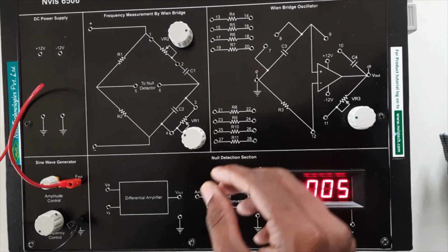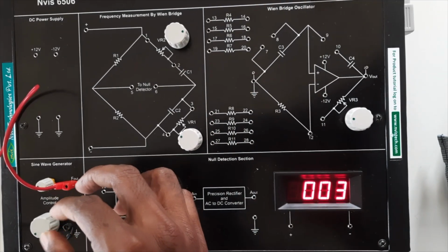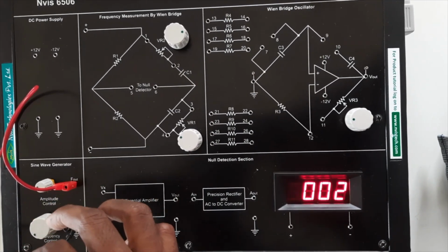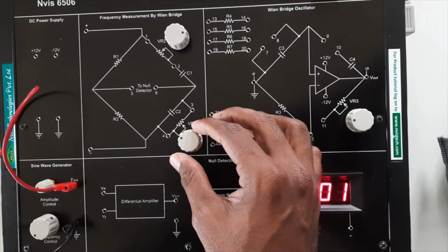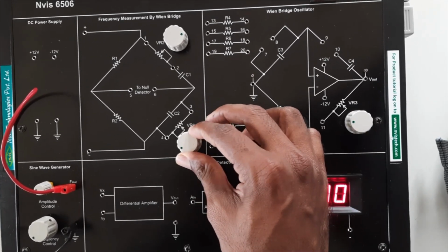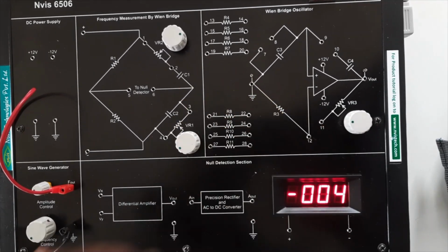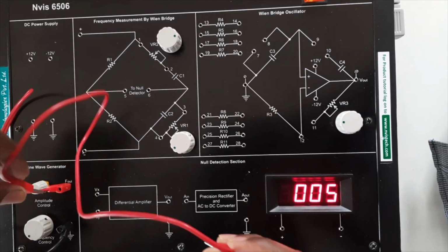Okay, so here we have set this VR2 as 160 ohms, and input also is set for 1 volt and 1 kilohertz, and this VR1 you need to change it from 0 ohms. So that's why first of all you need to keep this knob at extreme left position in anti-clockwise direction. Okay, now you can go for connections.